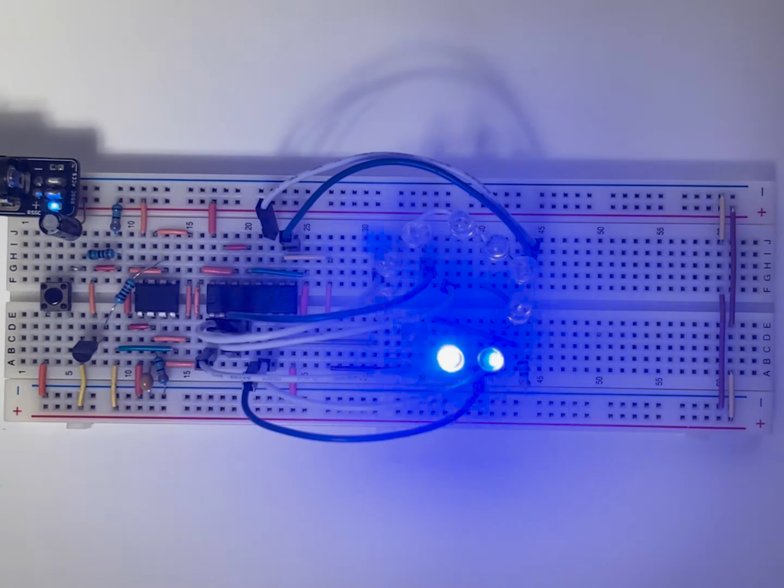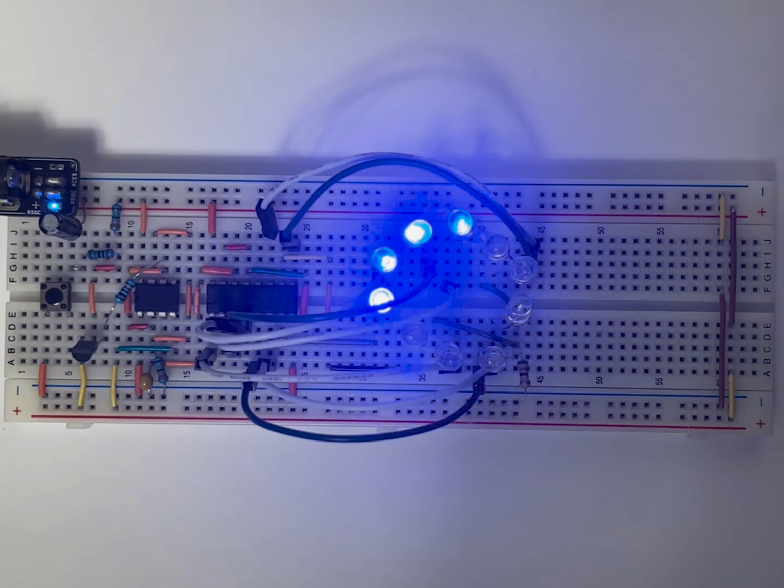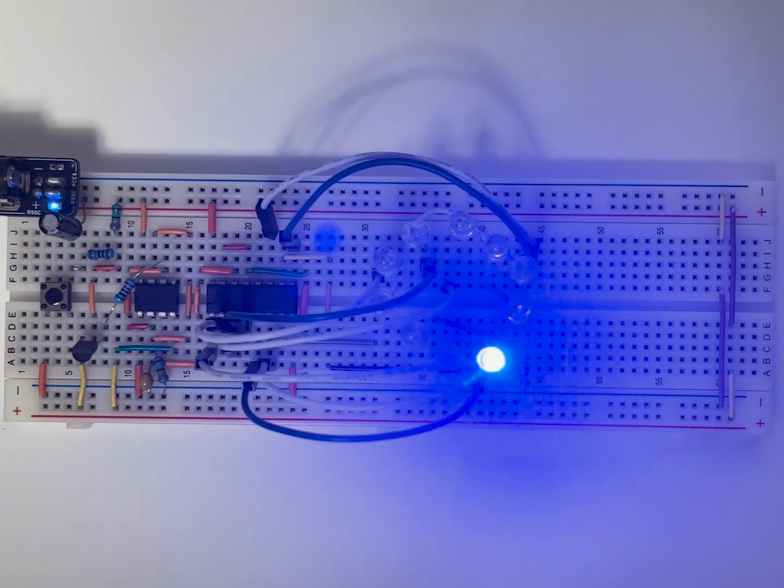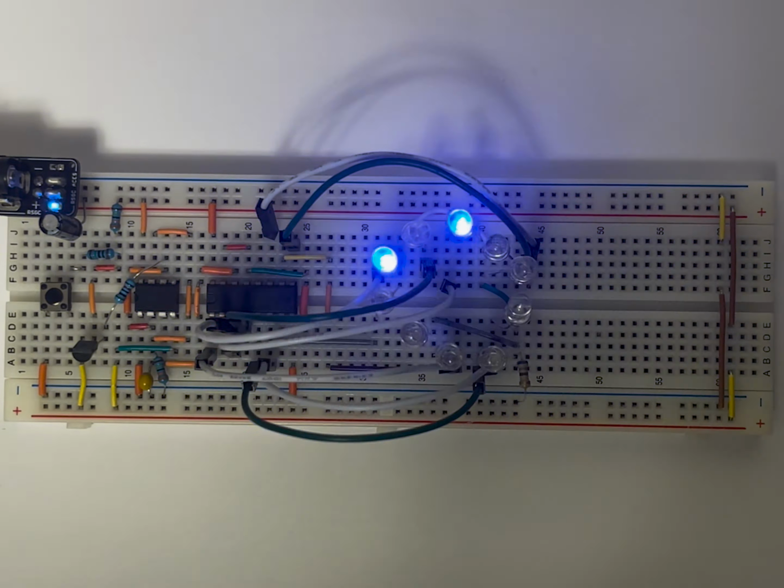First, the rate at which the capacitor discharges through the resistor network is subject to small variations in component tolerances and electrical noise. Second, and mainly, human reaction time. When releasing the button, it introduces an unpredictable delay. Together, these factors create a pseudo-random effect. Even though the sequence follows a set order, the precise moment when the wheel slows and stops varies with each activation.